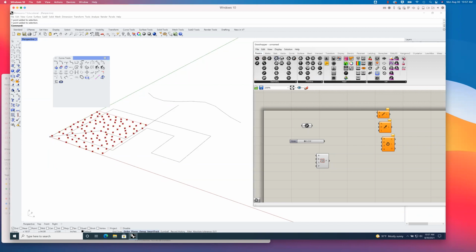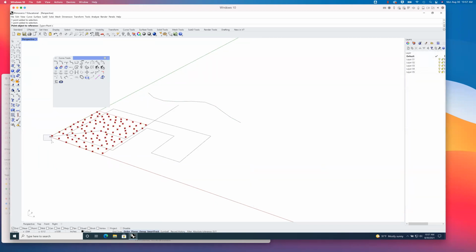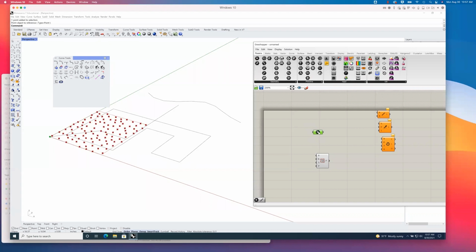And let me just bring that into Grasshopper. So I'll go to my params tab. I'm just going to delete some of these extra widgets that I have on here, right? These nodes. I'm just going to right click on that point and say set one point and go ahead and select that point that I modeled in Rhino, right?